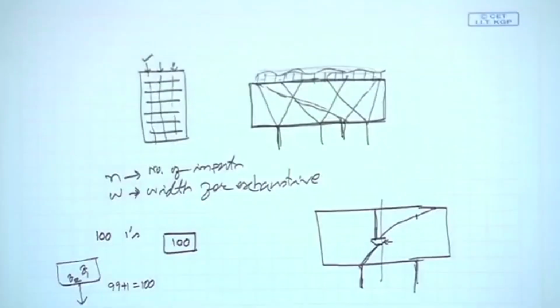So, the one count decreases, as a result the one count finally remains at 100. So, we see that this particular situation is not caught, it is a faulty circuit, but the fault is not detected by the system. Okay, so, that is called aliasing. So, faults are getting aliased.